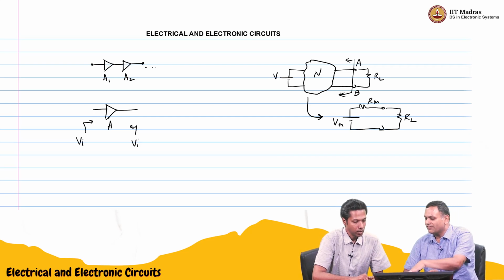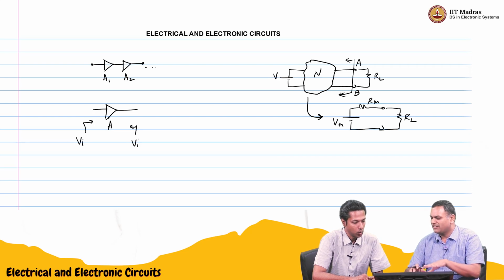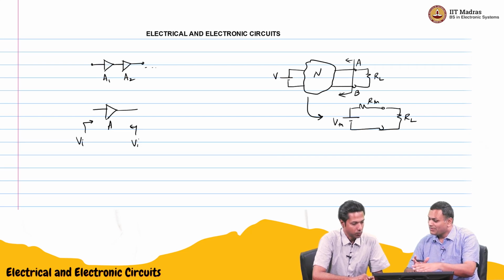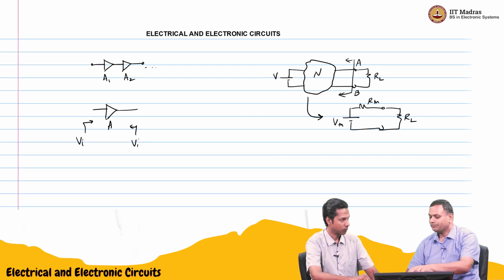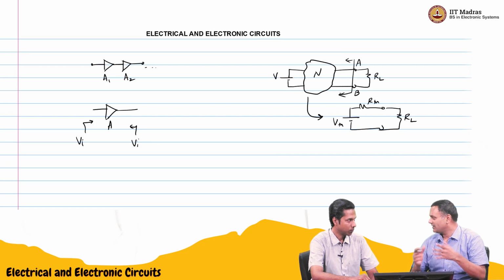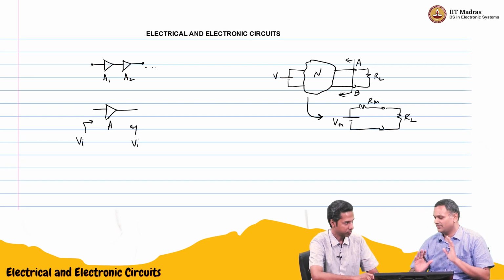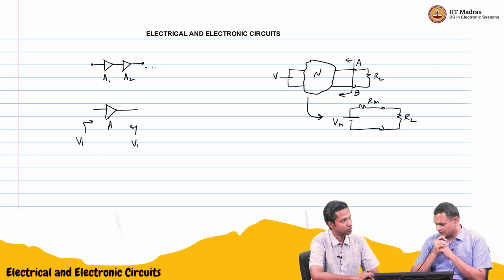In the case of Thevenin, what we did was we had some voltage source, or maybe even several voltage sources. We pulled them all out and used superposition. The network had some resistors, sometimes even AC resistors, capacitors, inductors. We found the open circuit voltage, and we de-energized all the sources and found the effective impedance, or resistance in the case of a DC network, across two terminals.